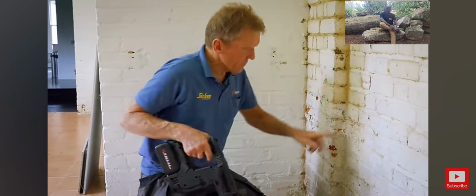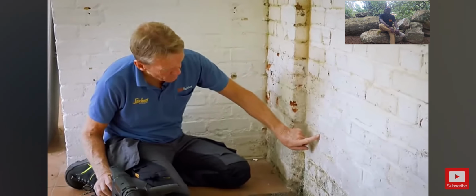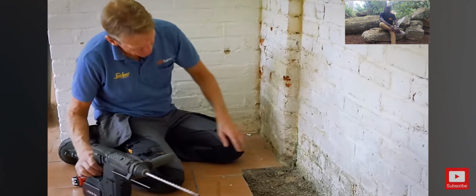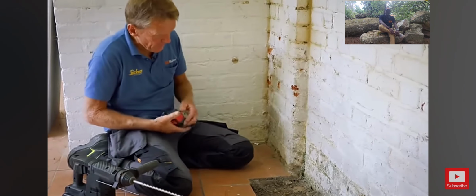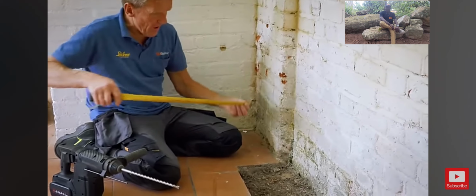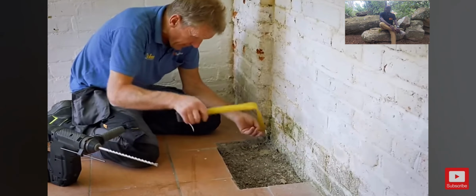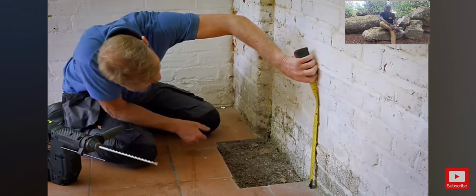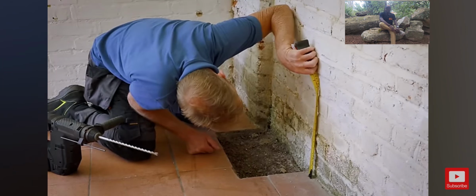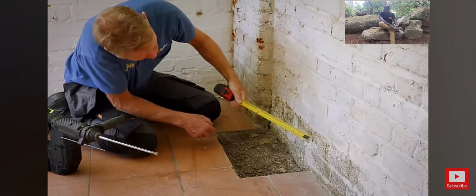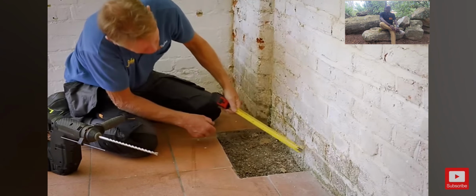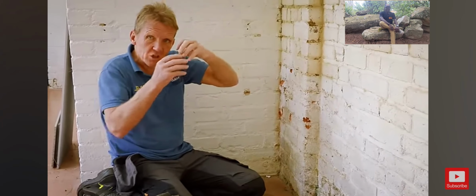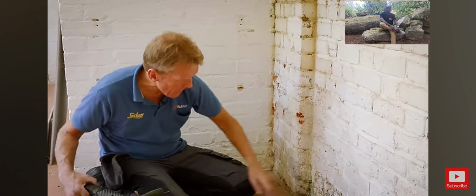What we're looking to do is, when you look at the mortar, you'll see a vertical joint there, which is what we call the perp, and you'll see the horizontal joint. So we want to be putting a hole in at every perpendicular joint we can find. Now I said 150 millimeters, so that would bring us in the middle of that brick, so we can go one above it or one below it. I don't think it matters too much which way we go, because the fluid does spread through. So let's go one above it.